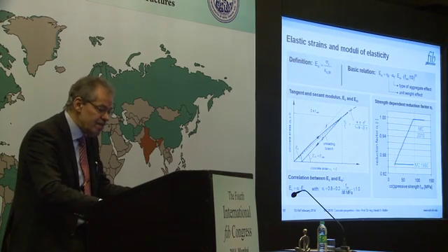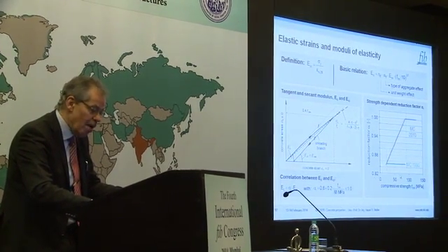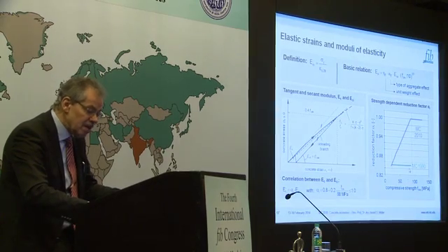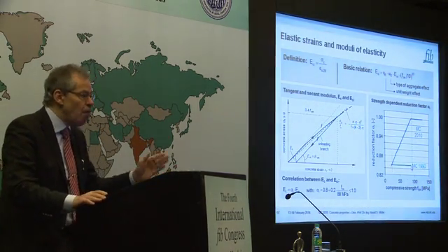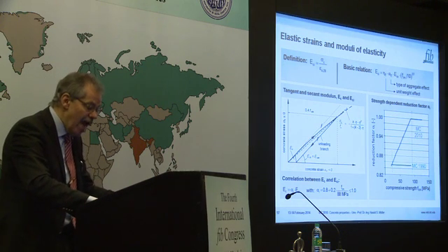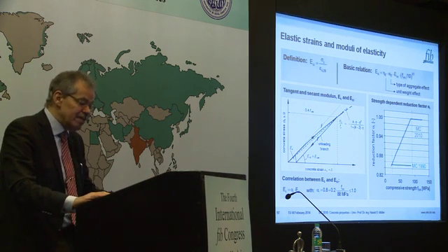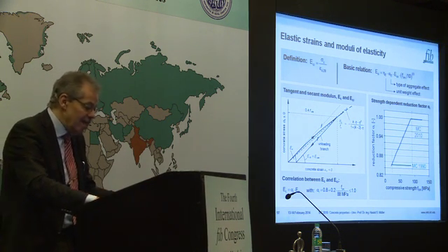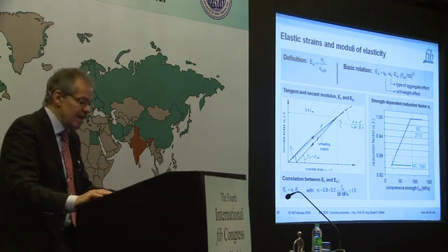And this reduction factor alpha is shown here over the compressive strength. In Model Code 90, we had just one constant value. It was 0.85. Now we have a transition from normal strength to high strength concrete. And if you have a concrete strength over around about 90 megapascal, then this factor is 1. You have no longer this initial set, these initial plastic deformations.